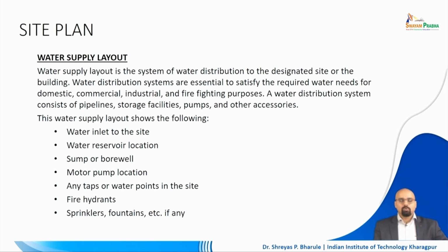Along with that, your motor pump location, so where will you be putting down your water pump or motor pump, that is to be laid out. Again, it should not be conflicting. If it is a submersible pump, it can go directly in the tank, but if it is a pump which requires dry surroundings, it cannot be submerged in the water tank, then you have to designate that particular space as well, as per client needs and requirements.